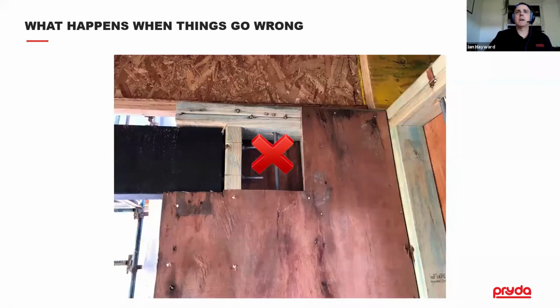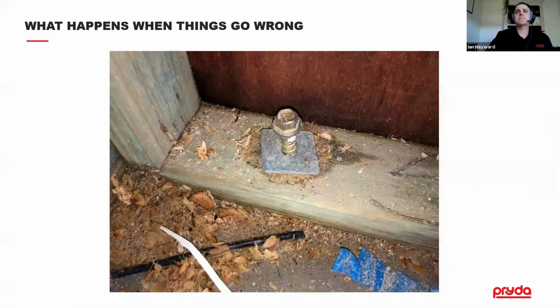Okay, don't drill or cut or notch any of these types of products. They're structural systems. Cutting out chunks of the plywood when it's in place just reduces the capacity of the system substantially. So don't do any of that. Make sure again, simple things, make sure all the tie down connectors are fully fixed off and in place.